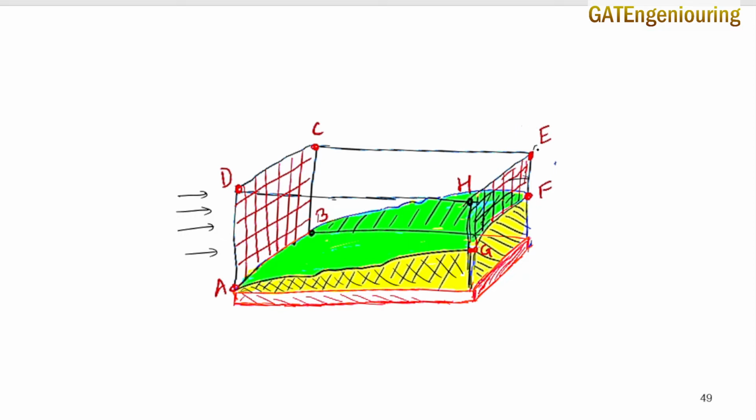To compensate for this decreased area, the free surface of the fluid flow adjusts itself in such a way that it increases its free surface height by an amount, let's say, the distance delta star. This delta star is nothing but the distance which is called the displacement thickness.